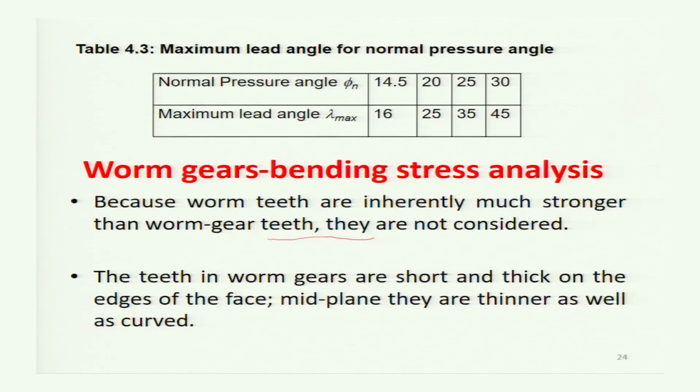Then the maximum lead angle for normal pressure angle. So, with the pressure angle of 14.5, 20, 25 and 30, the maximum lead angle that can be taken is 16, 25, 35 and 45.